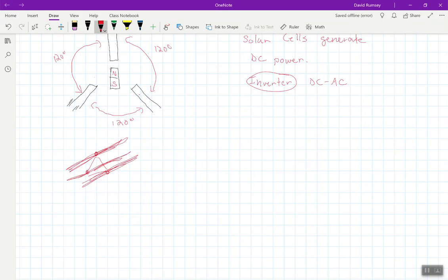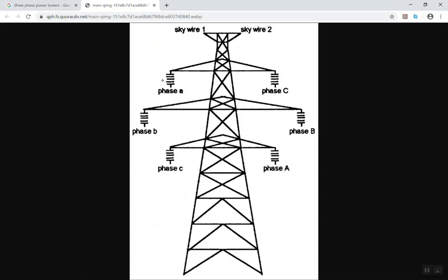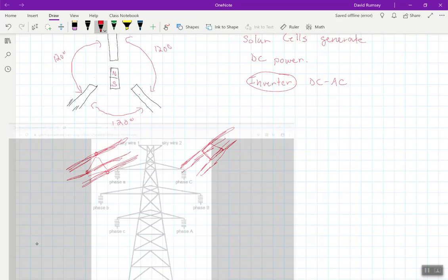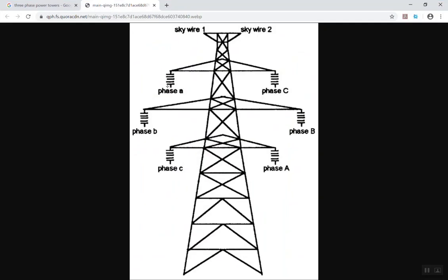The ones I've seen more recently in the towers that have been built in my area are diamond-shaped ones that have four conductors on them. So there are four wires coming off of these, in a diamond shape. And again, those four wires would all be in the same phase, connected to phase A. So sometimes people get confused and think when they see three wires together like this, oh, those are the three phases. No, those aren't the three phases. The three phases are these separate ones here.